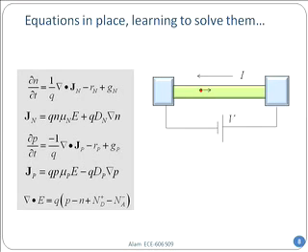How so? Isn't there a recombination rate present there, R sub n or R sub p? Well, yes, but remember, in Shockley-Read-Hall recombination, I will replace that term as np minus ni squared divided by the big denominator. So that term inside it actually only has n and p. So I can forget about that.